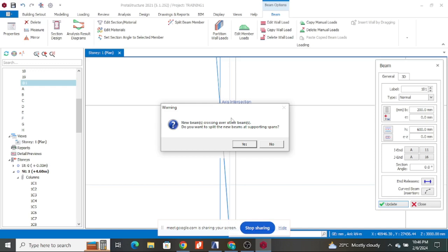What will be affected is the labeling of those beams. It will still model the same. The only difference is that it will give you a beam that has many sections, like beam 1, beam 2, beam 3. All of them are one part of one beam, which is continuous. Which is still okay.